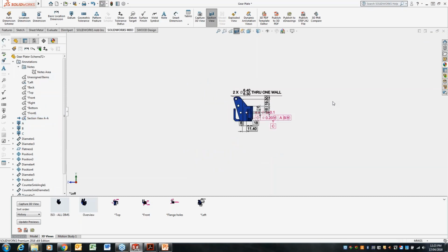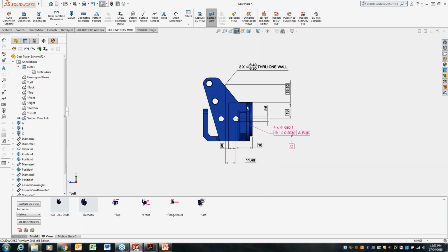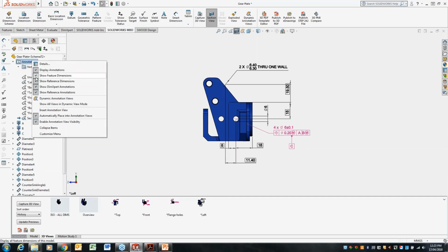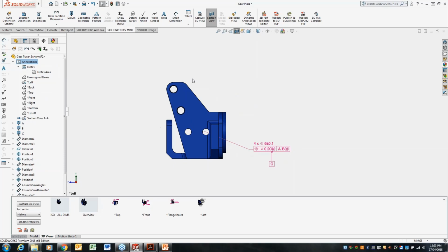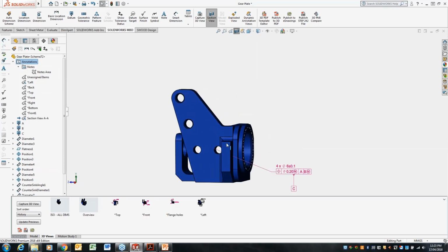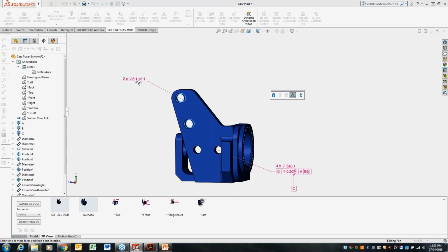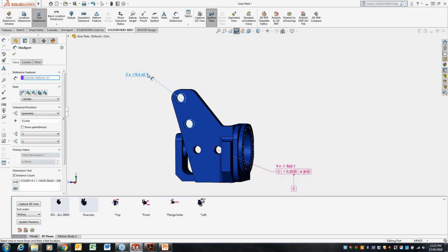You orient it to the section view now. Now, you don't need all the feature dimensions showing up, so you take off that. And you can see here, you have the earlier populated PMI for this hole here, but you want to have the details about this hole. So I'll just go on to size dimension, and it's already identified there are 2 holes of the same diameter. So it's given me that.